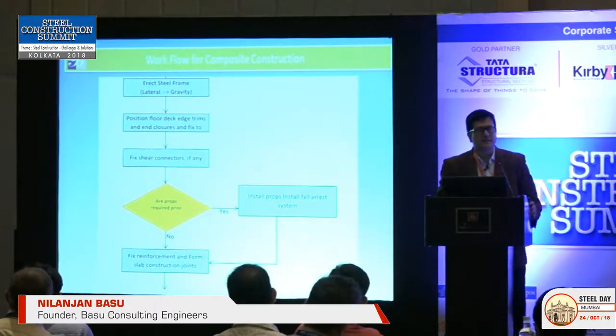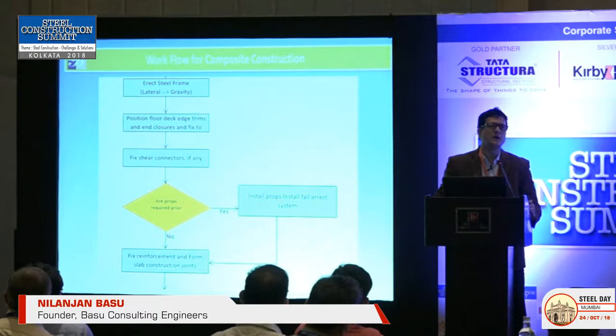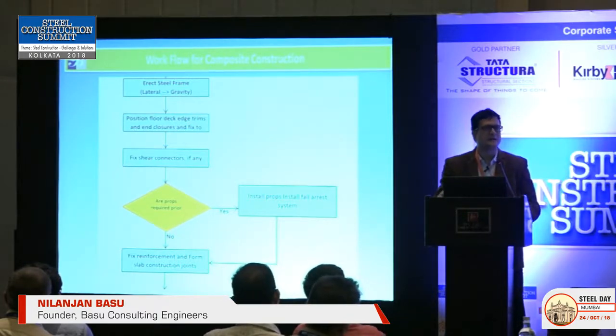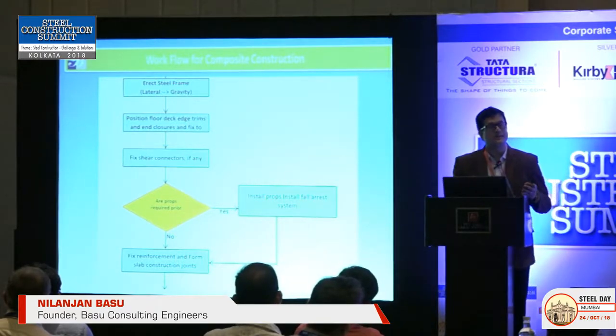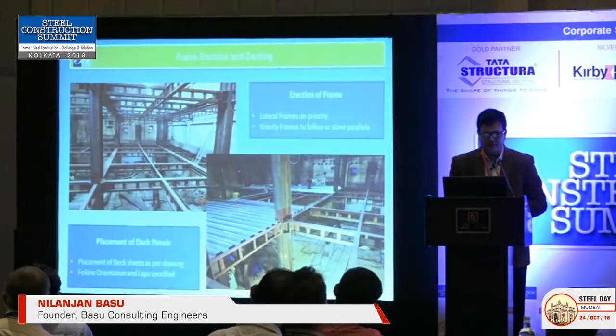During construction of a composite building, during the green concrete stage, there is no composite action. And you have to understand that, I know we are using a metal deck, but a metal deck and a beam can be subjected to a deflection due to a pre-composite dead load or a pre-composite live load. So do we put a prop? Yes, we can put a temporary prop. But what the prop does is, it avoids any cambering of the beam which is required.